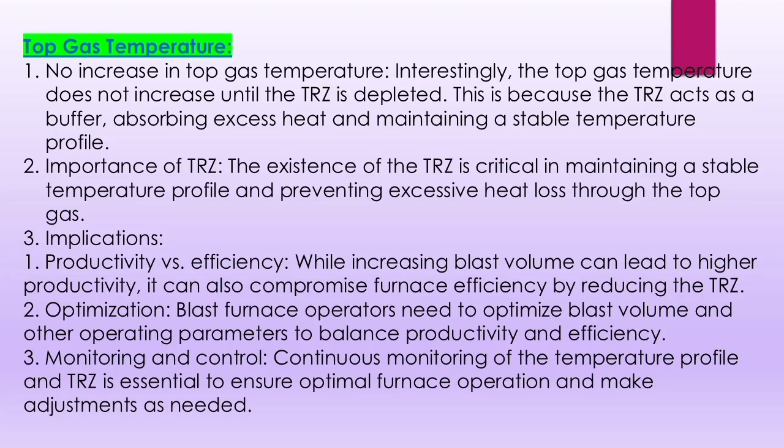3. Implications. Productivity versus efficiency. While increasing blast volume can lead to higher productivity, it can also compromise furnace efficiency by reducing the TRZ. Optimization. Blast furnace operators need to optimize blast volume and other operating parameters to balance productivity and efficiency. Monitoring and control. Continuous monitoring of the temperature profile and TRZ is essential to ensure optimal furnace operation and make adjustments as needed.